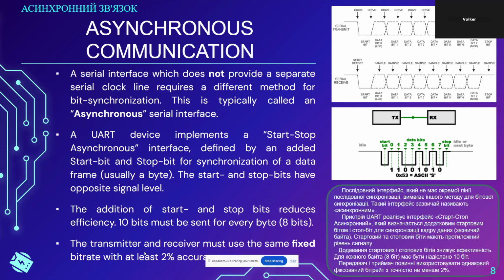Every time a new byte starts, there is a guaranteed forced signal edge, a negative falling signal edge, between the stop bit from the previous byte and the start bit of the next byte or data frame. The receiver will expect this falling edge to start its own clock generator.